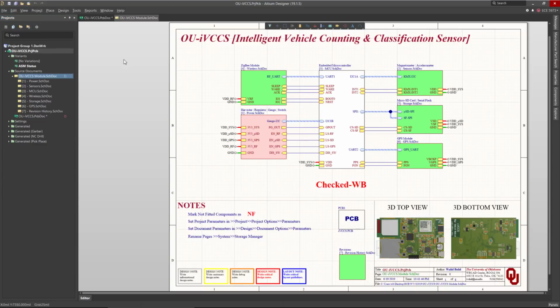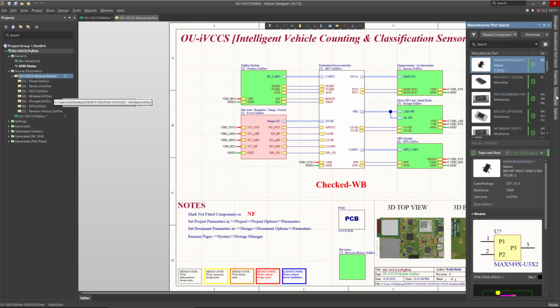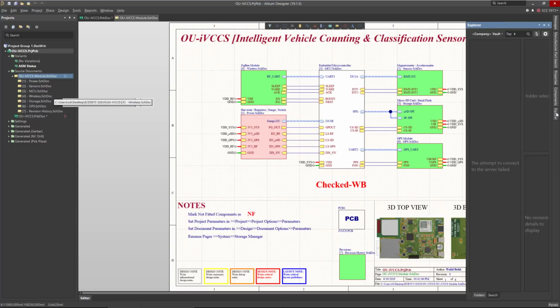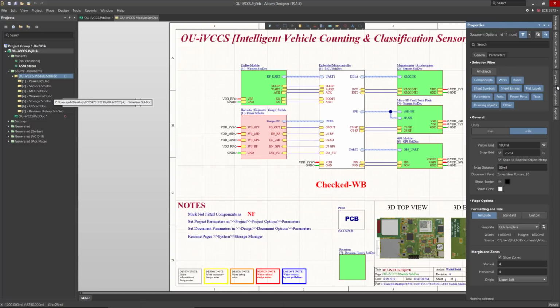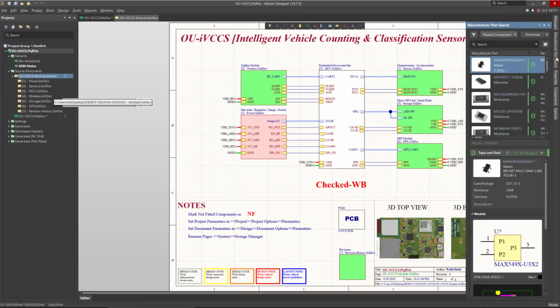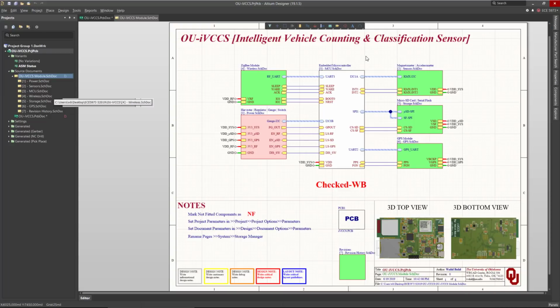Now the second docking mode is the pop-out mode. So in the pop-out mode, the panel will appear as a tab on the application border. So either on the left side, right side, or bottom or top, any one of the borders depends on where you dock the panels. So here we have 1, 2, 3, 4, 5. Moving the cursor over the panel tab will result in the panel sliding out from the border, as we can see in here. Moving the cursor away from the panel will cause it to slide back again.